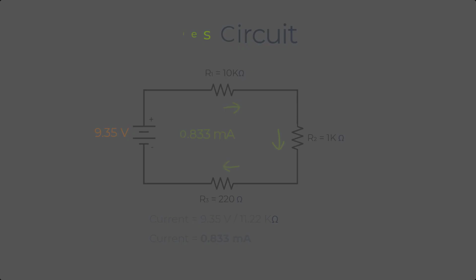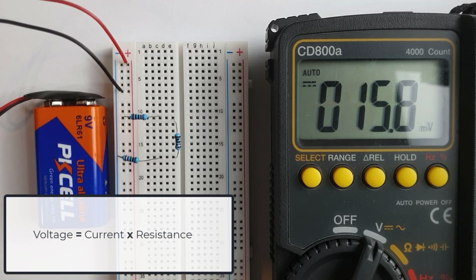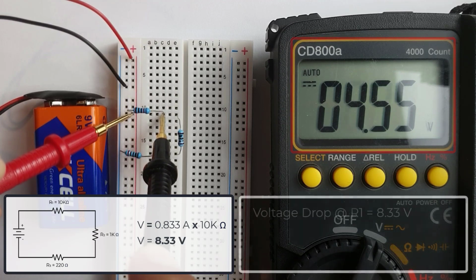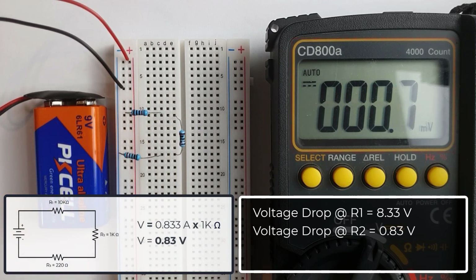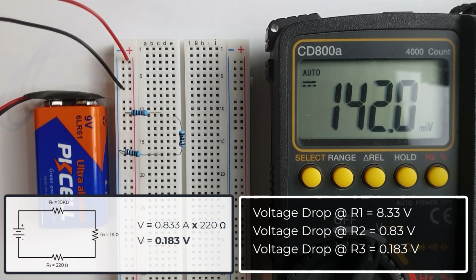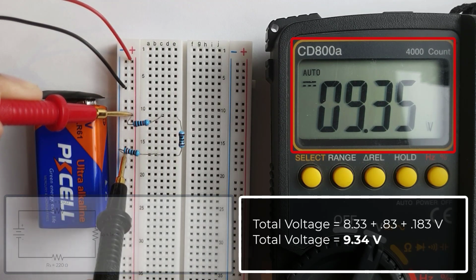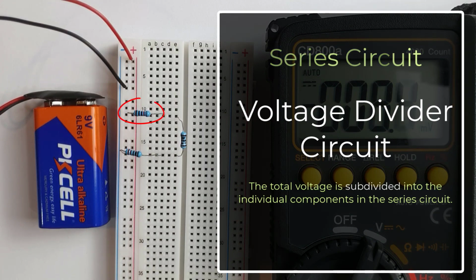So technically, we don't even need this multimeter to know the individual voltage drops across each resistor, because we can simply compute them using the formula voltage equals current times resistance. For example, the voltage drop on this 10 kilo ohm resistor is 8.33 volts. For this 1 kilo ohm resistor, the voltage drop is 0.83 volts. And for this 220 ohm resistor, the voltage drop is 0.183 volts. And we know that these individual voltage drops, when added, will result to the total supplied voltage, which is 9.35 volts. That's why a series circuit is commonly known as a voltage divider circuit, as the total voltage is subdivided into the individual components in the series circuit.